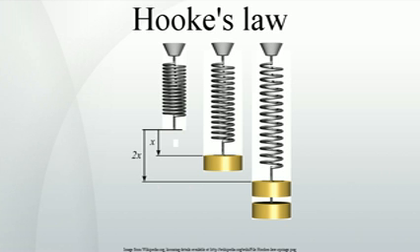General tensor form. Some elastic bodies will deform in one direction when subjected to a force with a different direction. One example is a horizontal wood beam with non-square rectangular cross-section that is bent by a transverse load that is neither vertical nor horizontal. In such cases, the magnitude of the displacement will be proportional to the magnitude of the force, as long as the direction of the latter remains the same, and its value is not too large. So the scalar version of Hooke's law will hold.